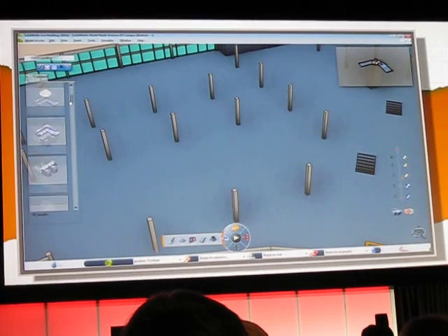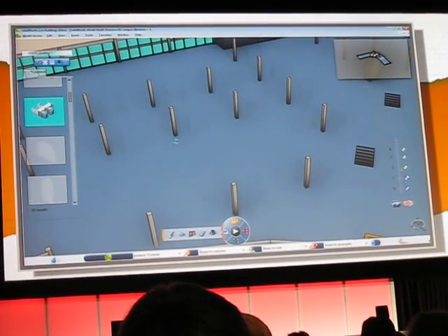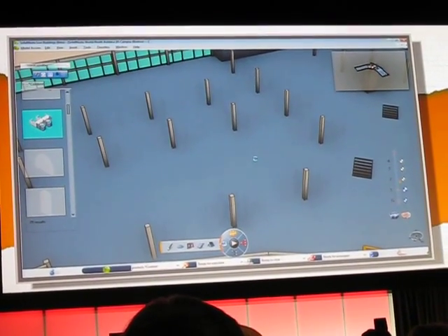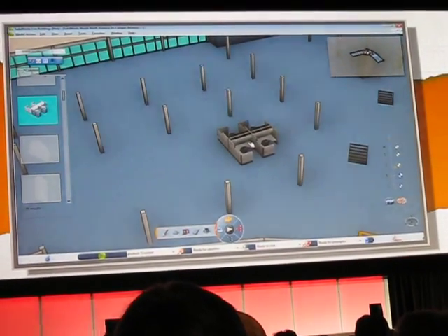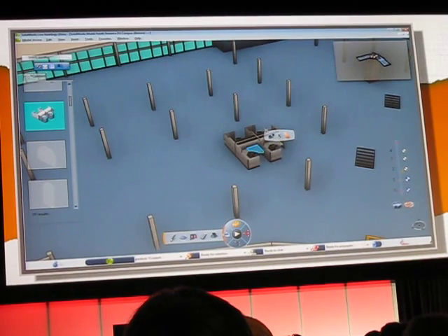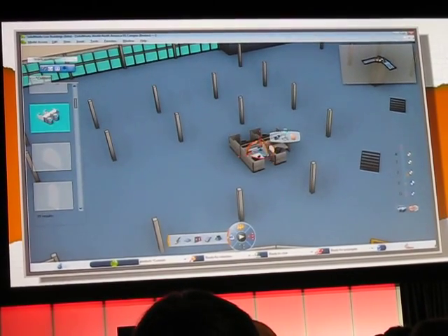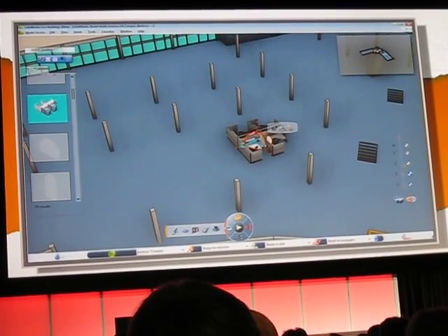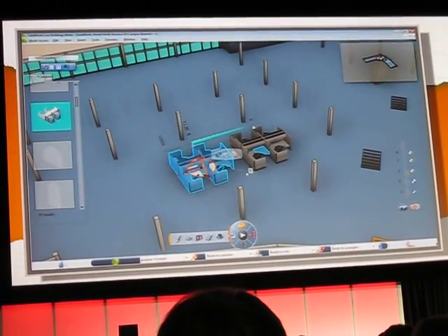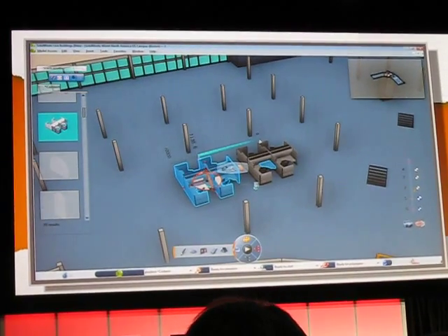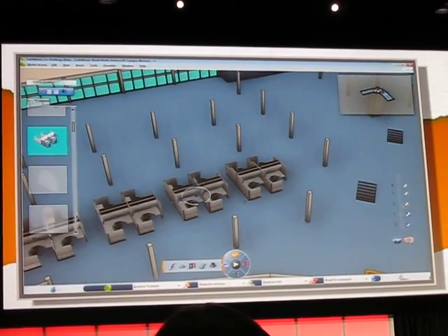So we'll take a look at the cubicle and just drag and drop that into the floor space. It uses a concept similar to SmartMate, so it knows exactly where it's supposed to go. And if you want to make a copy of that, we'll simply use the triad, as we saw previously, and just drag it over to the left. So you see, very quick, very easy, a very nice conceptual tool for designing office space. We can also use the concept of patterns to update this design as well.